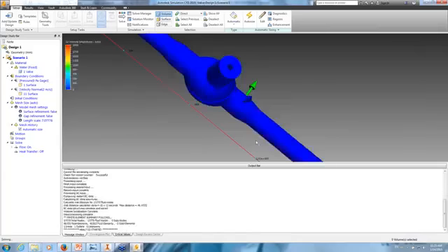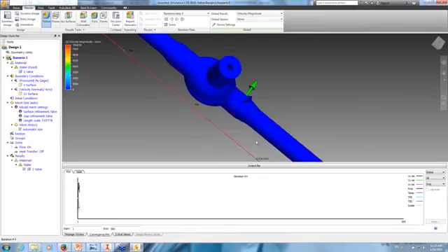It's going to create the mesh and start doing the iterations. And by default, the mesher creates a boundary layer mesh at the walls. You have 3 layers. This way, you will have at least 3 nodes to capture the flow and the transition between 0 velocity and whatever the actual velocity was going to be. Basically, to capture the boundary layer effect.